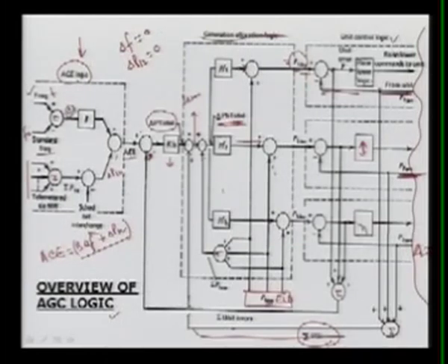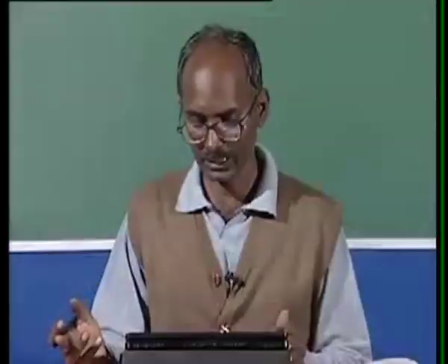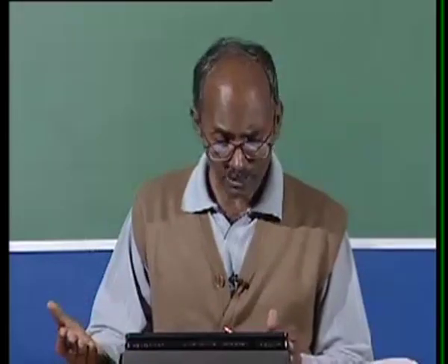In economic load dispatch logic, we have to reset because once the load is changed, we are going to share the load. Why not? We have to achieve the economic loading of these generators, and then we can get the minimum cost of generation. So the combined logic of this AGC plus ELD I also discussed, and so far we discussed only the frequency control, and then in the next lecture we will see the voltage control.